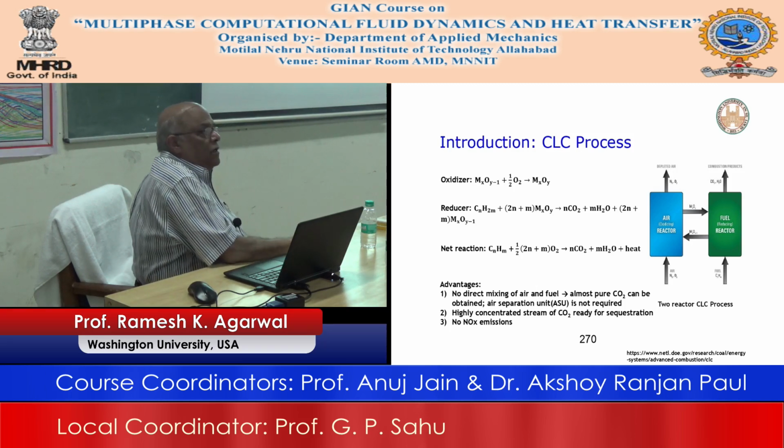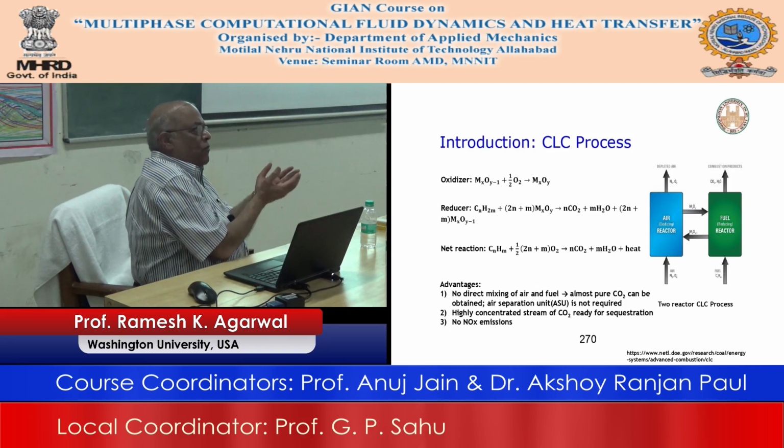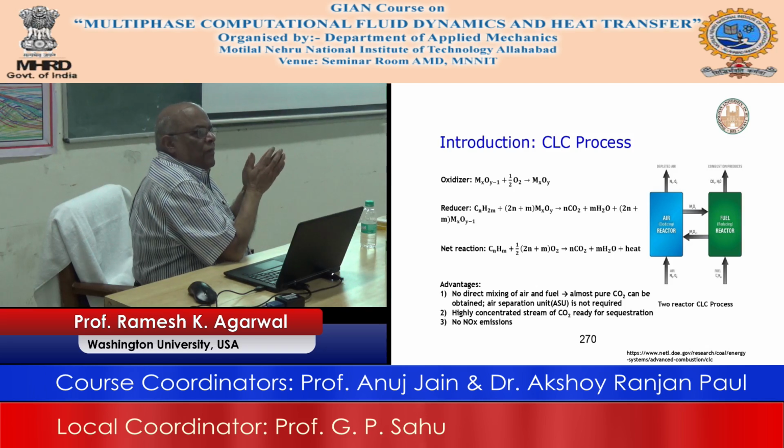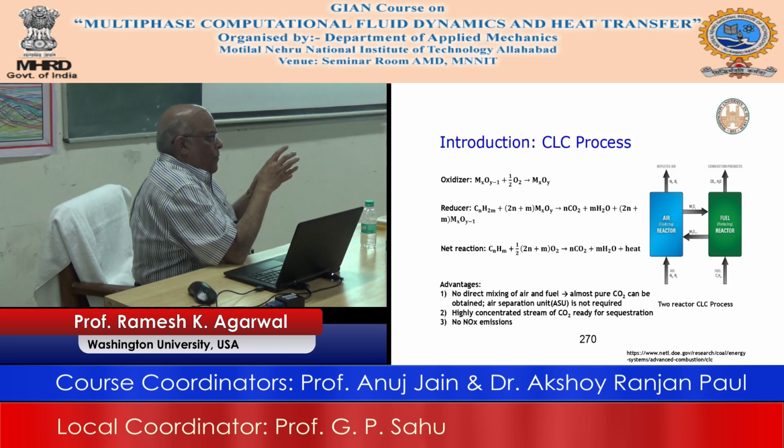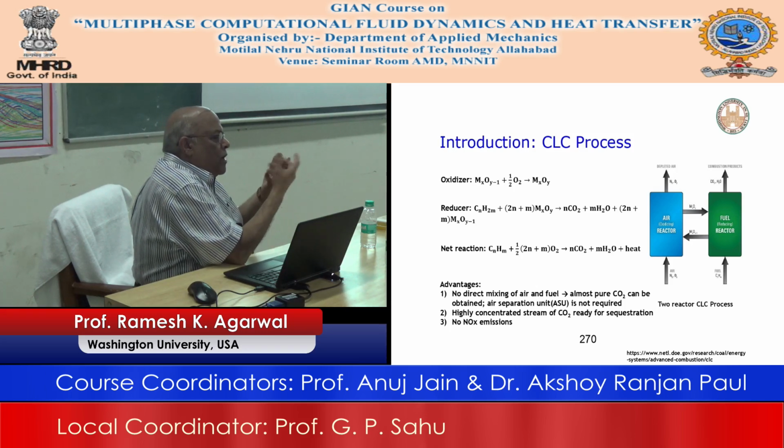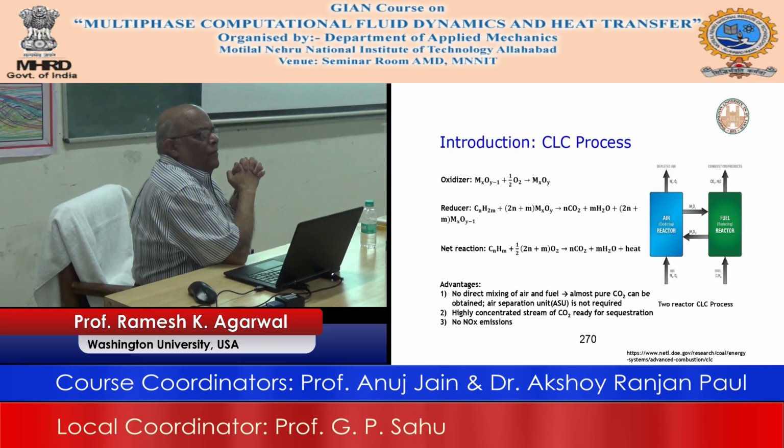The advantage is that when you burn it at 900 degrees, there is no nitrogen at all. You have only coal, and this oxygen carrier decomposes. Once it decomposes, Fe2O3 becomes Fe3O4 plus pure oxygen. That is one way to create pure oxygen inside the reactor.